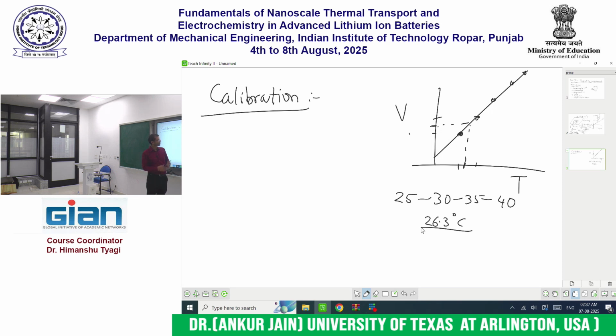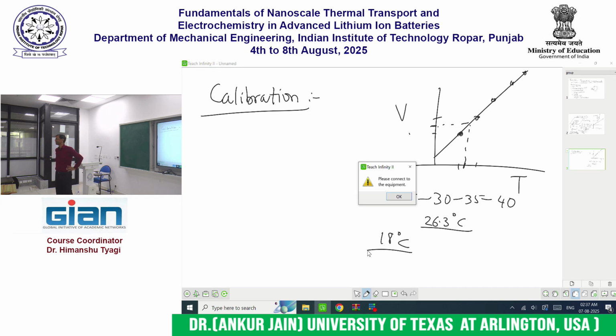I also cannot use it to measure a temperature of 18 degrees Celsius, because 18 degrees Celsius was never included in the range in which I measured the temperature during calibration. Okay? And the big challenge with calibration is that it requires me to provide a well-known temperature of 20, 30, 40, etc. degrees Celsius.